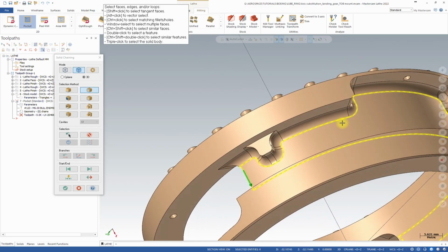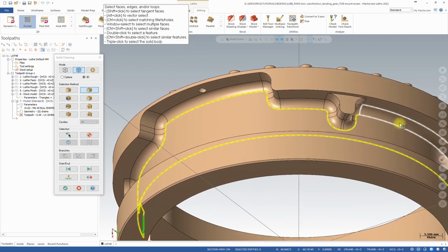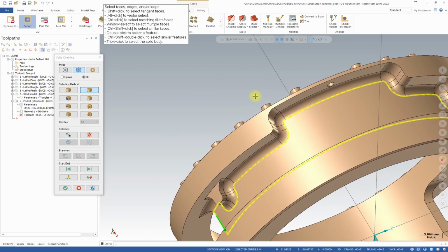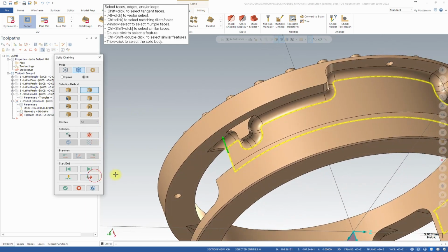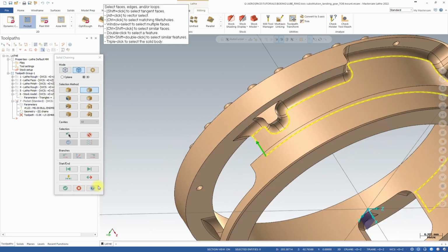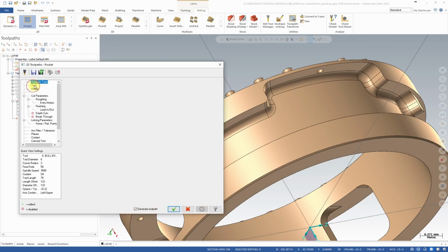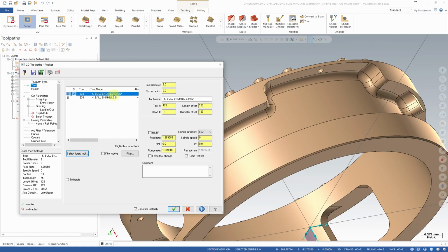As you see, the chain selected doesn't include the radius, but every radius on this channel is the same, so all radii are 2 mm. As my tool, I'm going to use a 6 mm bull end mill with 2 mm radius. Let's set some feeds and speeds. We have to use something, so let's say 1000 for feed, and then spindle, let's put it as 4,500.